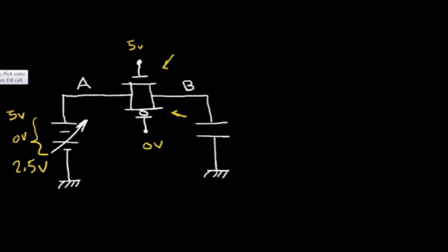So in a typical circuit, we might give this terminal a name. And if this voltage is high, our switch is closed. So let's label this node with the name close, which infers that a high voltage signal causes this NMOS transistor to close, but we also want the PMOS transistor to close.